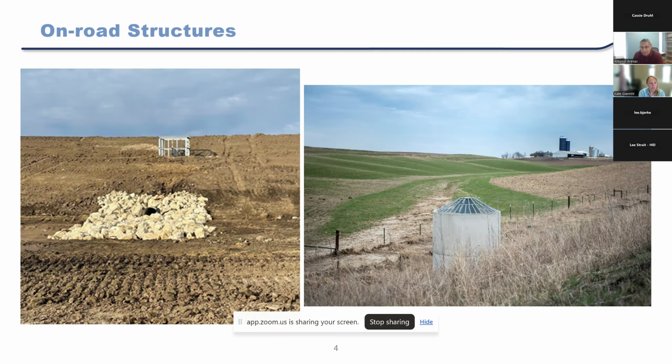So in this particular picture, if you look at the left-hand side, for example, water that moves towards the road has two ways to continue moving downstream and to pass to the other side of the road. One would be through the pipe at the bottom, which is relatively small, at least if you think about traditional designs. And then at some point, there's a riser pipe that is activated if the water gets high enough.